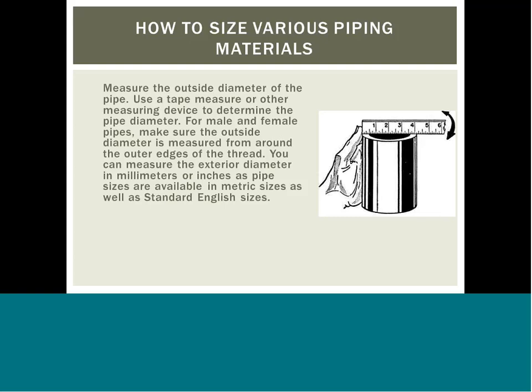Choose a pipe fitting that corresponds to this pipe size. Pipe fittings go over the pipe, so it is the external diameter that is important as the fitting goes over the pipe. Match the connector type, as there are pipe connectors specifically for male threaded pipe ends and female threaded pipe ends. Some pipe connectors will not use threads, but will be marked as a female slip fit or male slip fit.